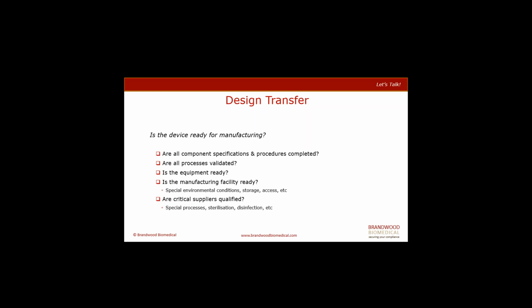For example, are there special environmental conditions that are required for the manufacture of this medical device? Or storage conditions, or even access? And are your critical suppliers qualified? Critical suppliers where a supplier may be producing a very complex component, or it could be that they're producing an important part of the actual product in the sense of a sub-assembly. Or it could be a process such as sterilisation or disinfection.